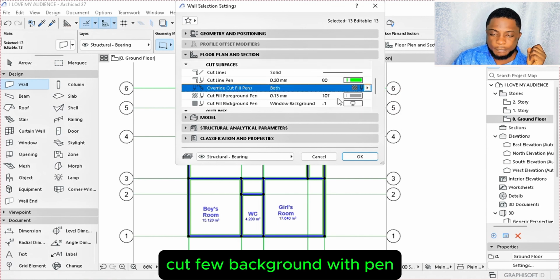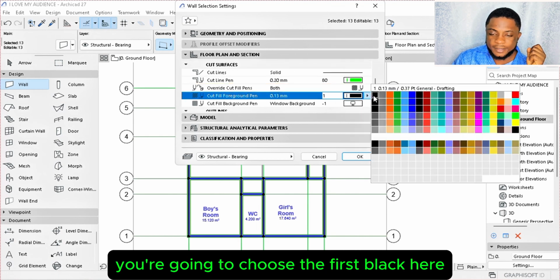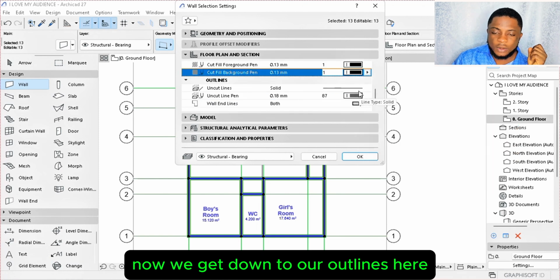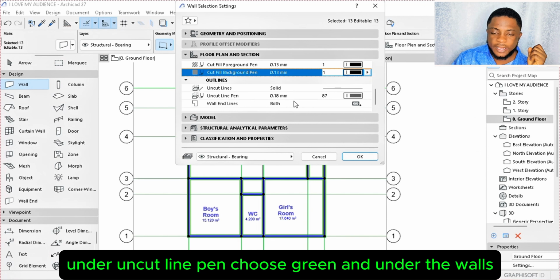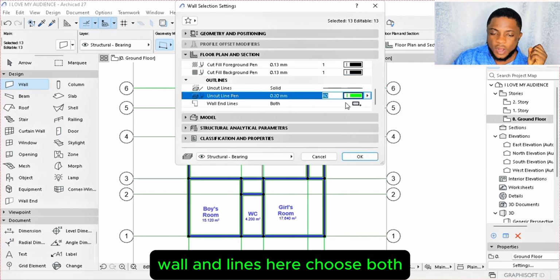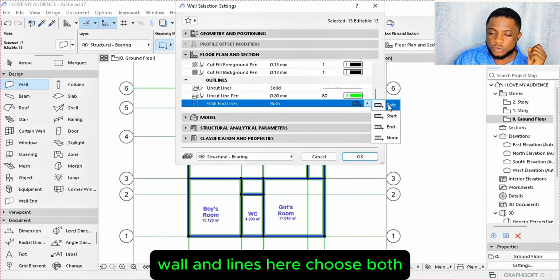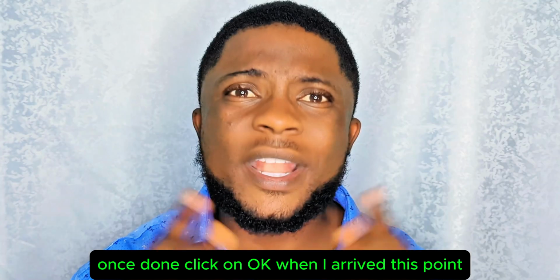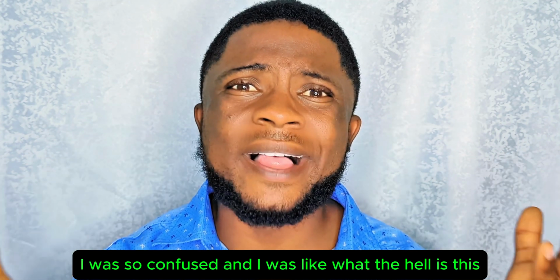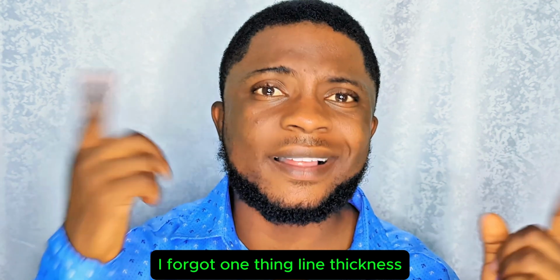Cut fill background with pen, you are going to choose the first black here, and down here you are going to equally choose black. Navigate down to our outlines here. Under uncut line pen, choose green, and under the wall end lines here, choose both. Once done, click on OK. When I arrived at this point, I was so confused and I was like, what the hell is this? I forgot one thing. Line thickness.